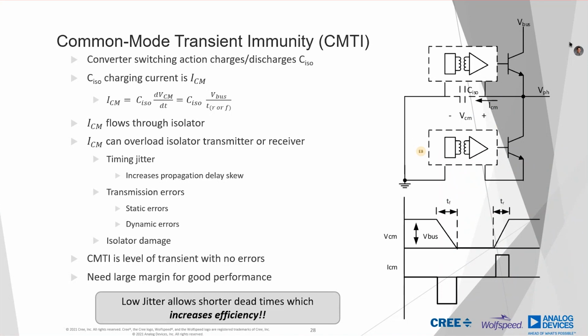Okay. And so focusing on the gate driver, because that can cause problems in the operation. You're having this common mode current that flows through the gate drive isolator, and that can cause problems with the isolator, especially if it's a capacitive isolator. Then you've got capacitance in the barrier. It looks like a capacitor. The current's going to flow right through it.